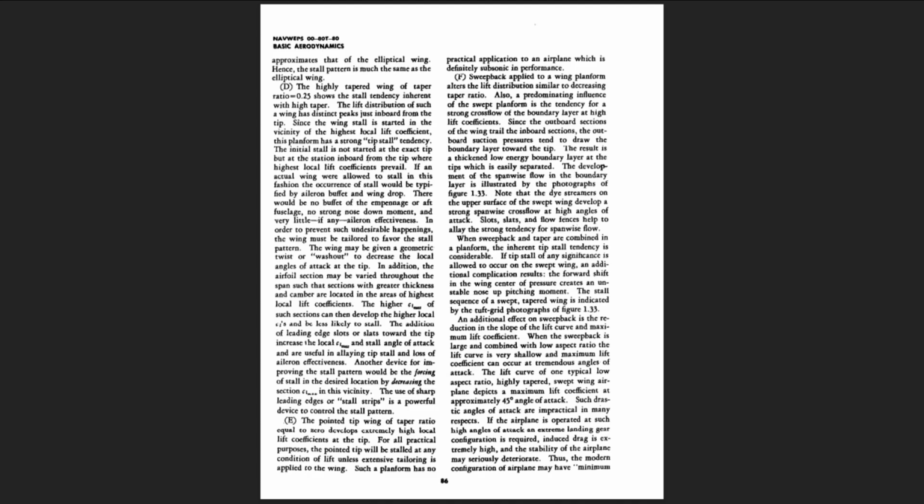An additional effect of sweepback is the reduction in the slope of the lift curve and maximum lift coefficient. When the sweepback is large and combined with low aspect ratio, the lift curve is very shallow and maximum lift coefficient can occur at tremendous angles of attack. The lift curve of one typical low aspect ratio, highly tapered, swept wing airplane depicts a maximum lift coefficient at approximately 45-degree angle of attack.